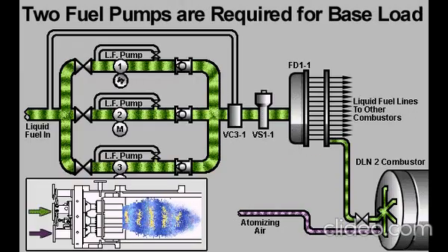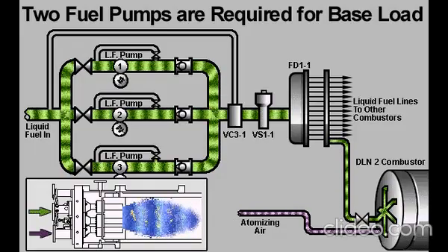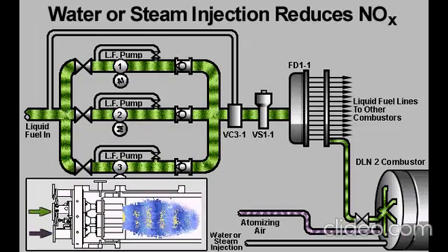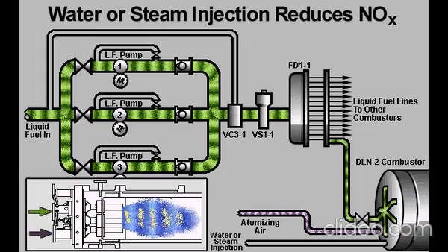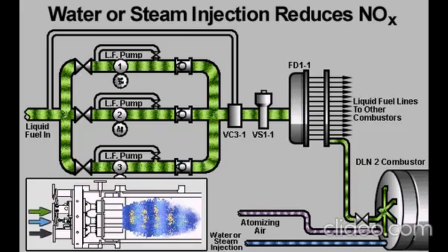During the gas turbine loading sequence, a second fuel pump is activated. Two fuel pumps are required for base load operation. The third pump serves as a standby pump. When operating on liquid fuel at base load, the system must use water or steam injection to reduce NOx emissions.